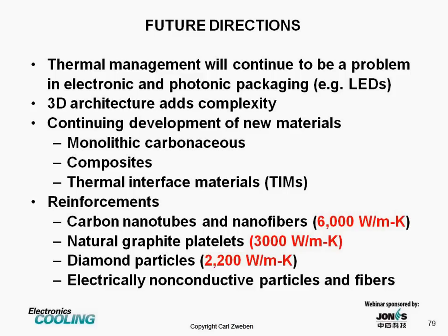If we look at reinforcements, carbon nanotubes and nanofibers have thermal conductivities as high as 6,000 watts per meter Kelvin. We comment on the carbon nanotubes: results so far for thermal management have been disappointing, largely because of the many interfaces arising from the small size of the carbon nanotubes, and that gives rise to phonon scattering.